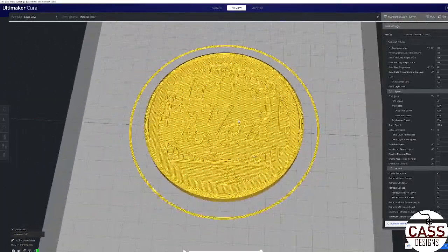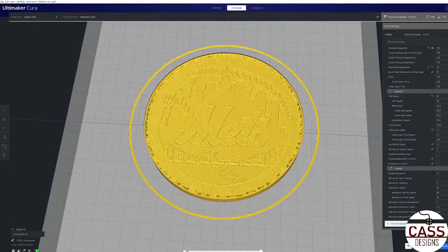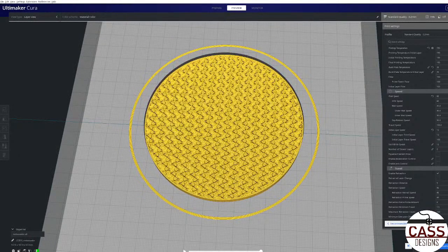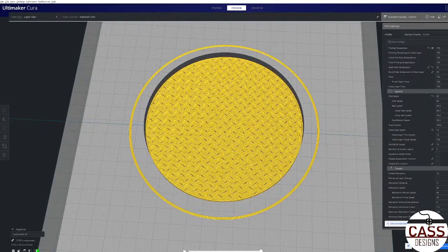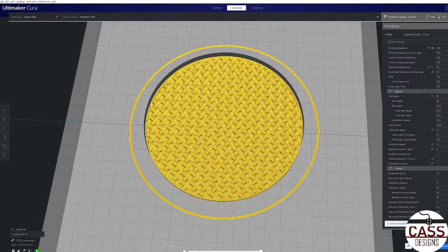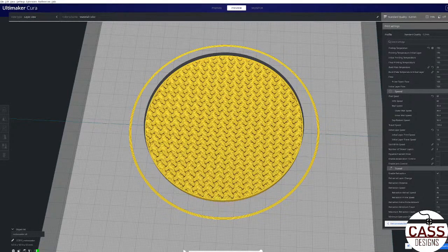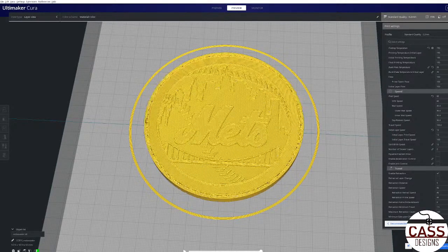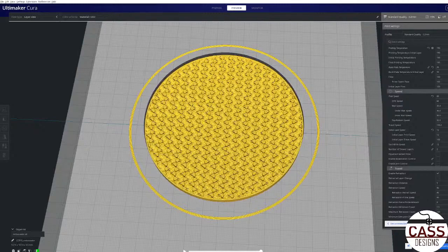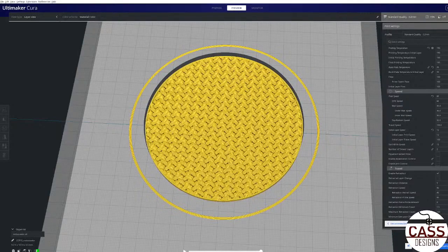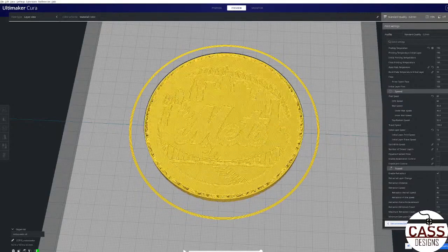So over here on the right of the screen, which you can't really see right now, I can drag to show the layers. So these squiggly lines are called the infill lines. You could 3D print everything 100% solid, not hollow at all and completely filled. But this saves you material, it saves weight, and it makes the printer print a little bit quicker.